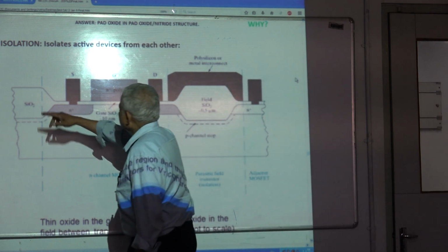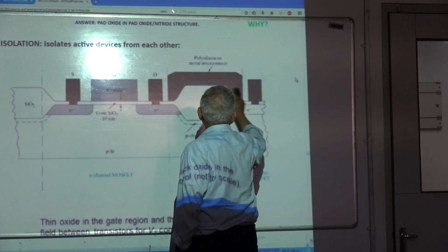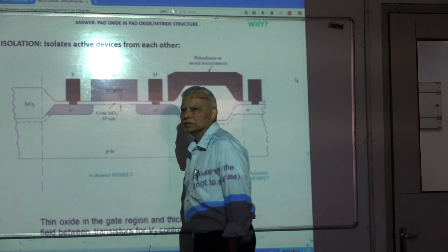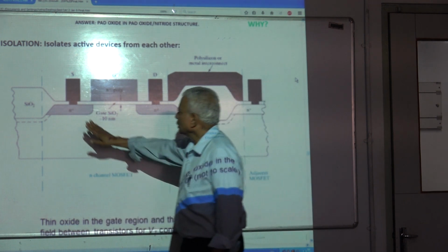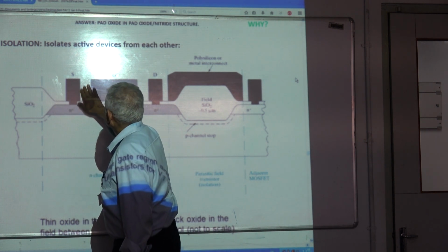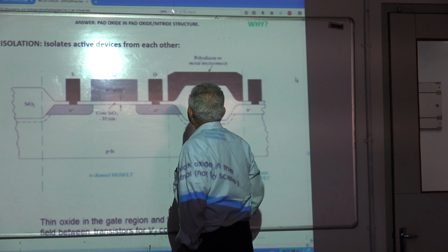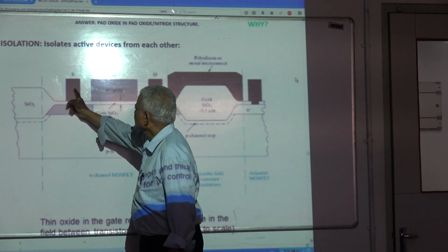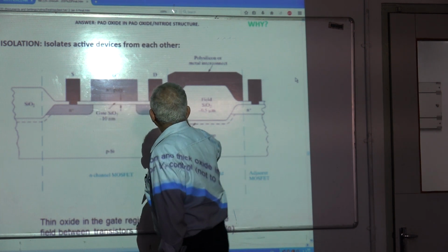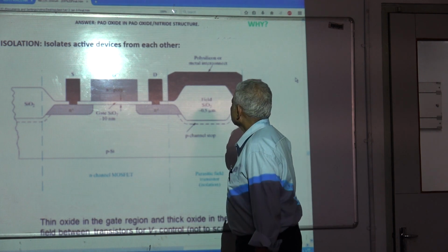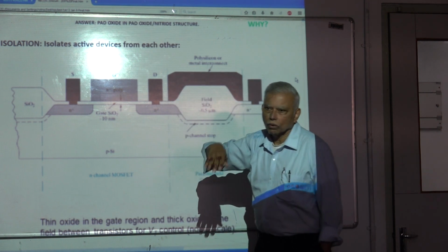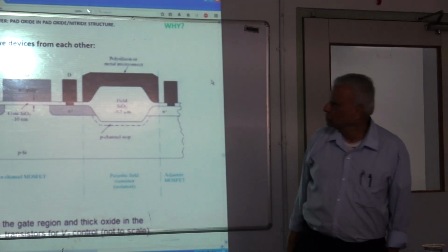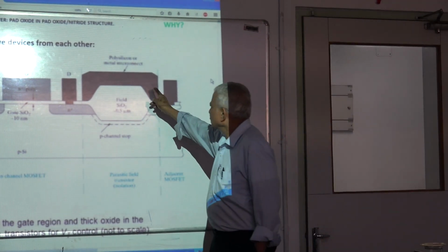And of course, I identified earlier that these are all isolation here. These are all oxides here, the so-called passivation oxides. Whatever you see, the open white region is all oxides. So you have those rows of oxides separating the contact from the gate, and you have other things like wiring, polycrystalline wiring, doped polycrystal, which is a conductor, very heavily doped. So you have the wiring that's going next to each other.